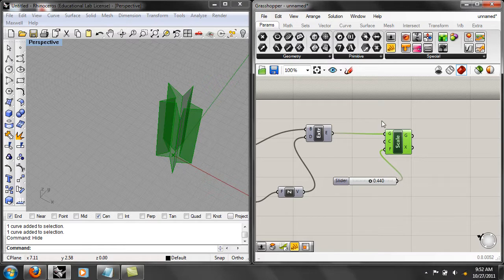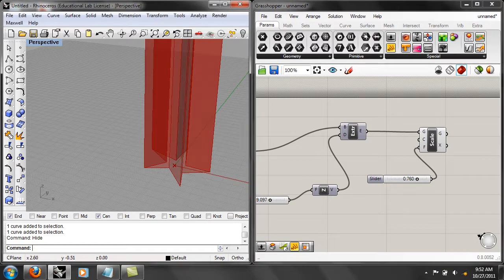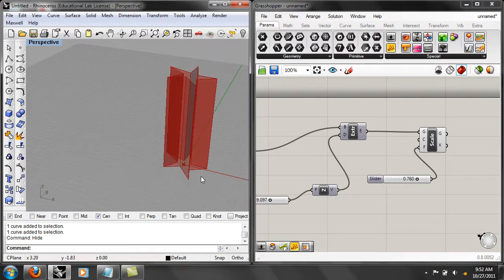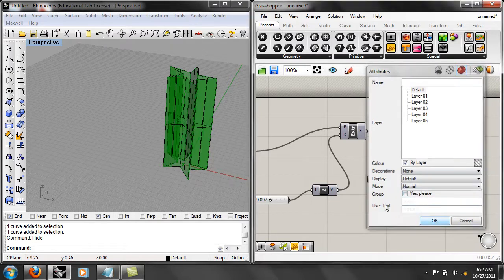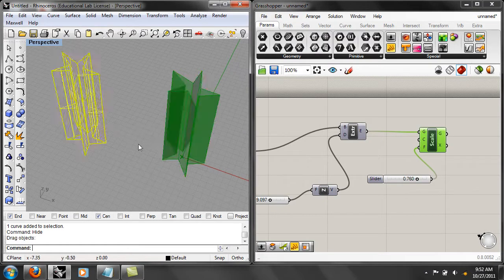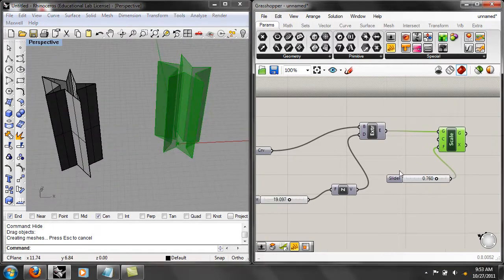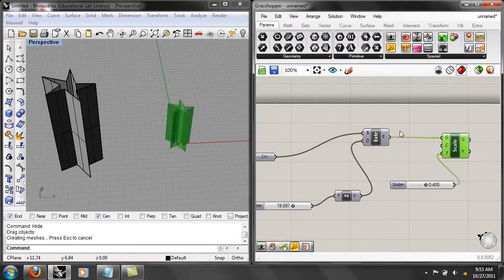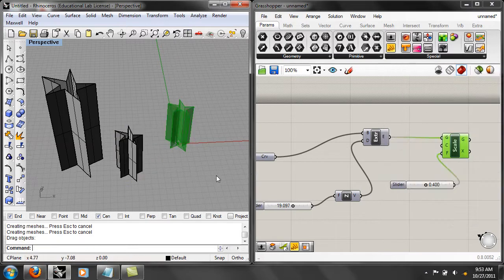And now, just to refresh your memory, I didn't talk about this in the demo, but how would I get this into my Rhino model so I can actually play with it? Bake it. And how do you bake something? Right click and then the egg, which I don't know why fried egg is the icon for bake, but we'll go with it. Maybe it's a baked egg. See, and now I have an instance of that. Now, if I change the size of it, I get a different one, okay?